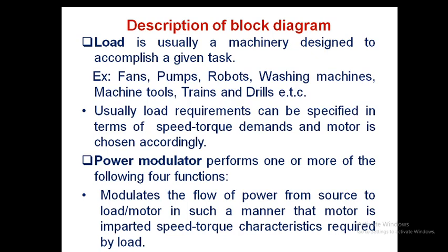At starting, do you require high torque or low torque? Whether your torque needs to be proportional to the speed or inversely proportional to the speed, or another requirement. Based on this load requirement we need to go for the selection of the motor.